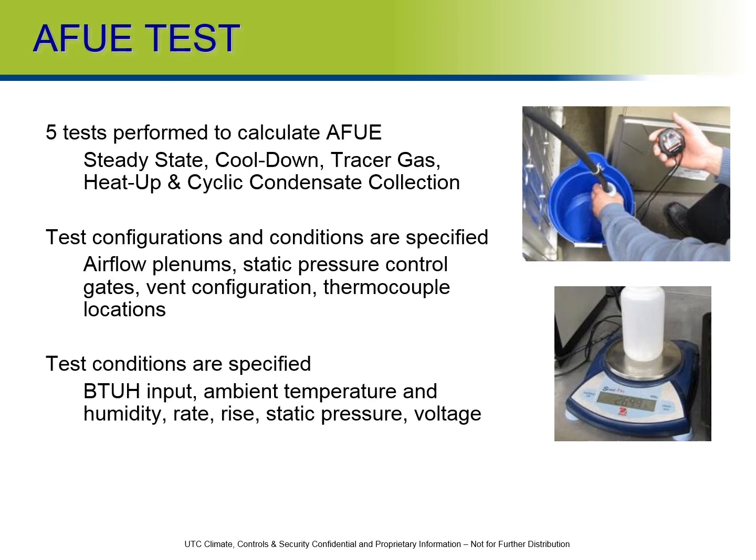Taking a temperature reading in a plenum directly above a piece of equipment allows radiation heat to affect your temperature reading. Radiation heat directly off of the heat exchanger will affect your temperature reading when you're taking a temperature in the plenum. Again, these test conditions are specified in the AFUE testing.